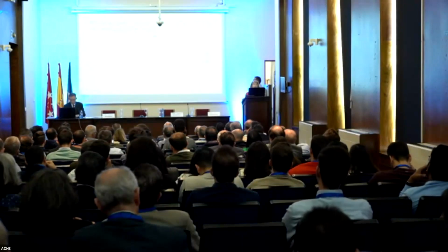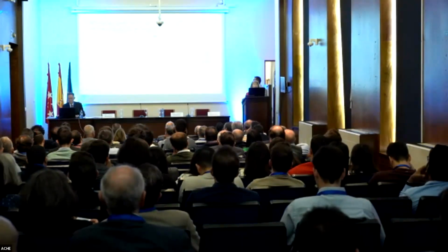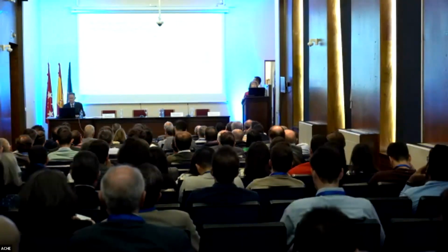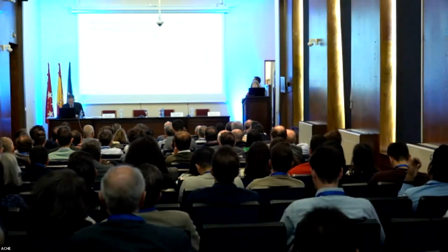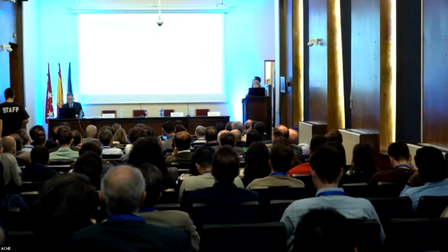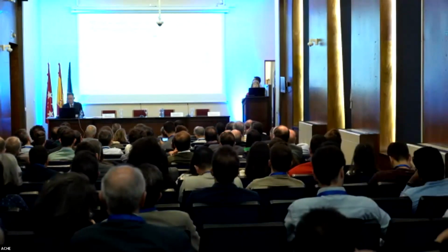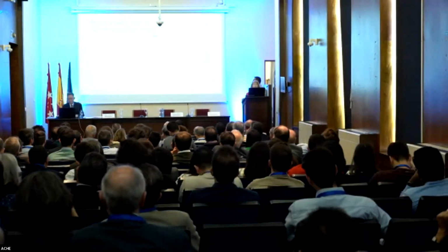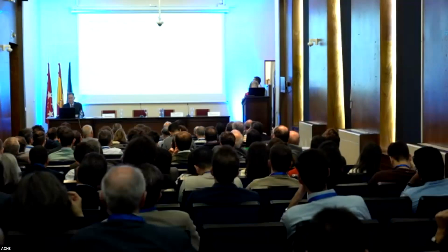The manner you select the cover is that you go to the exposure classes. After, you had to select a structural class for reinforcement or for pre-stressing, and after with that you have the cover depth, and also with the cover depth and the exposure classes you have the mix proportions in EN 206. Well, now all of these structural classes disappear, and the new concept of exposure-resistant classes appears.